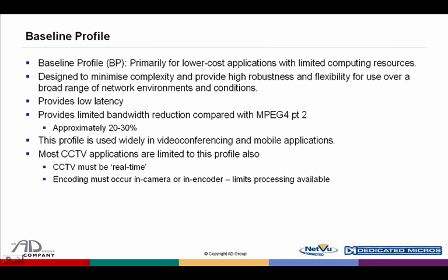It's also the profile that's most widely used within CCTV applications, again driven from the fact that we need CCTV to be real-time or very near real-time, so we can't tolerate high latency. Also, the encoding must be done typically in camera or in encoder in a CCTV system, and therefore that's going to limit the processing power available at the camera.